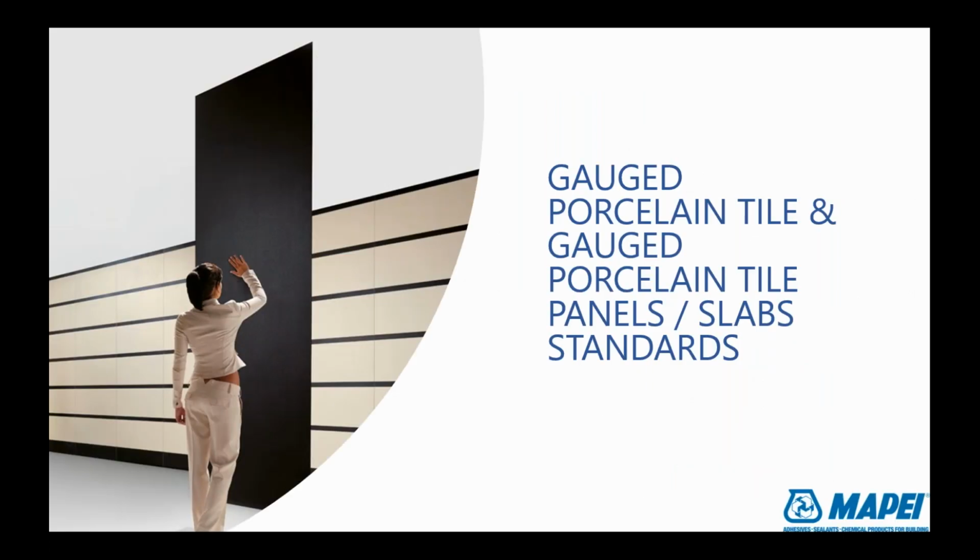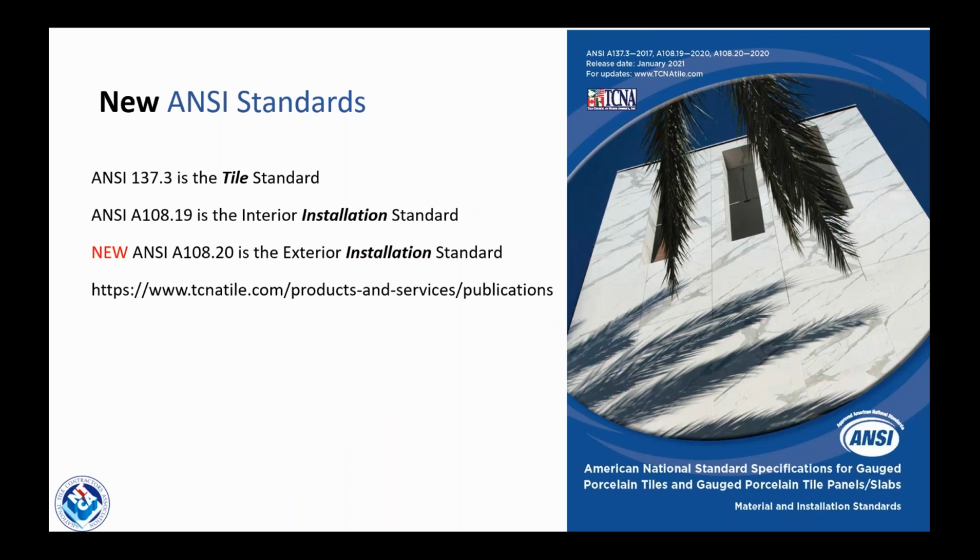Let's talk a little bit about gauge porcelain tile and gauge porcelain tile panels / slabs and the standards. These are all fairly new standards. ANSI A108.20 is the tile standard. So how to produce the tile, how much strength it should have, how much for impact, how much for modulus of rupture, et cetera. That's within the standard. We'll get into that in a little bit more detail.